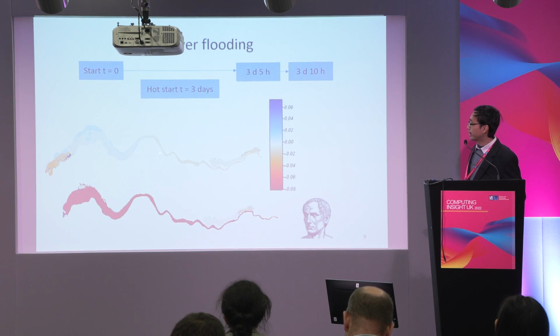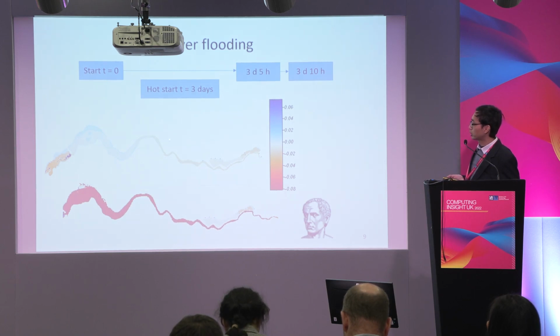So what is the hot start file in this case? We stored only the water level for the hot start because originally this CoSeC flood model does not allow us to run from a hot start file. So what we do is we store it as an output file and then use that output file as an initial condition for the new runs.